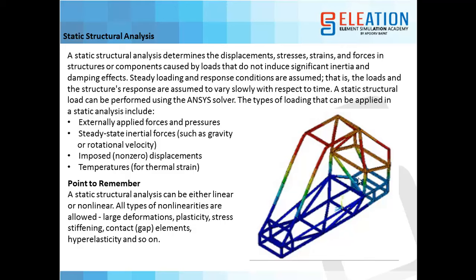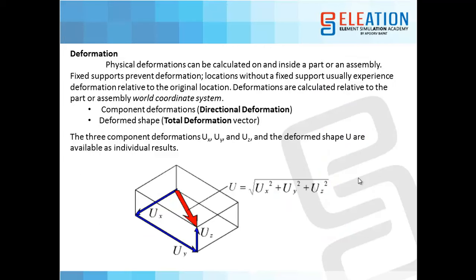That is the condition where I consider my object in a completely static domain and it is not moving. So whatever the force or pressure or movement or temperature which I am going to apply, I am considering that they don't change with respect to time. They are constant, or they are for some particular time. So whenever I don't solve any models where forces are changing with respect to time, I do static structural analysis. So mainly we see deformation and stresses in static analysis.